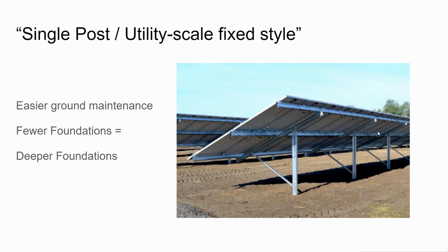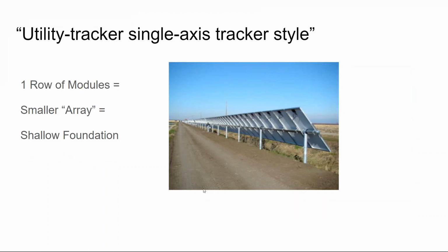Well, that's not completely true. It goes substantially deeper if you have two panels stacked. If you just had one panel stacked, you wouldn't need as deep of a foundation. And so then you get into utility scale single axis tracking, and it's only one panel, and so the posts don't go quite as deep as something that you would get with pile driven.